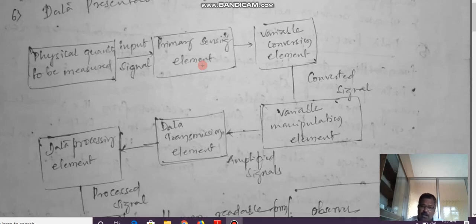One sensor converts the weight to strain, and the other, the strain gauge, converts the strain to the electrical form, that is, in the form of resistance, by using the Wheatstone bridge. Then the resistance is converted into a low level voltage that can be read in the electrical form. So the data gets manipulated, transmitted and processed. The overall point is that once you add an input in a physical format, it is converted to the electrical format. That is what the sensors are used for here.